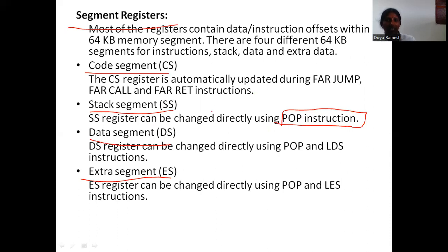The DS register, that is the data segment register, can be directly changed by using pop and LDS instructions. The extra segment register can be directly changed by using pop and LES instructions. LES means load extra segment, and LDS means load data segment.